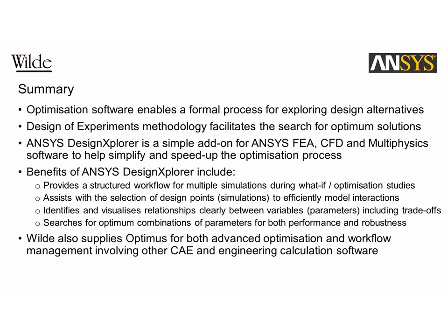What we've also talked about is the sampling of design points to understand which combinations of parameters you should use when running your simulations. And a range of techniques and a range of algorithms within DesignXplorer to help you choose those sampling points intelligently to both efficiently model the interactions you're likely to get between your parameters, to efficiently understand what's going to influence the design and obviously hopefully drive to an optimum, whilst also being able to minimize the number of simulations you actually have to run.